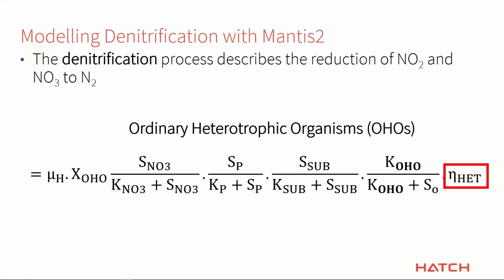And this is going to basically dial back the growth rate. So it's the same proportional growth rate, but when it's in an anoxic zone, it only goes at 30 or 40% of the speed that it would when you're running it in an aerobic environment. So if you're trying to calibrate your denitrification and you don't want to mess up the rest of your model, you can come and adjust this parameter. And then that will adjust just the denitrification part of it by itself.